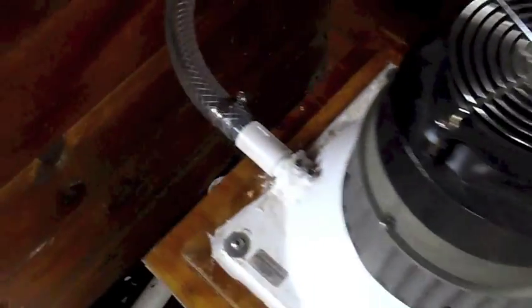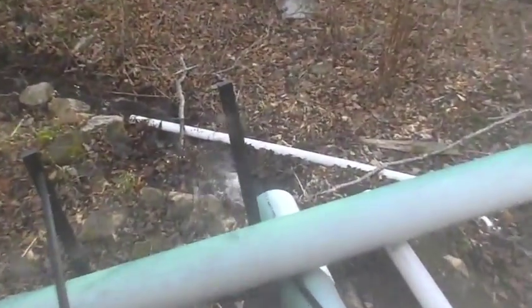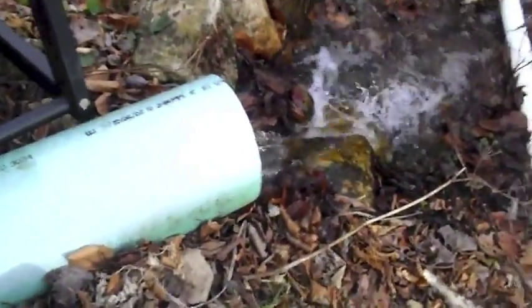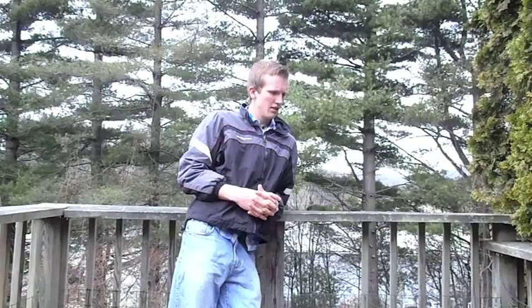When water reaches the end of the penstock, it then flows through this pipe that I show here, then down through this tube, and then is distributed throughout 4 nozzles in the Harris hydro system. Water then goes through the bottom of the turbine, then flows out through the tail race. And as you can see, since all the water is redistributed back into the stream, there is no ecological impact.